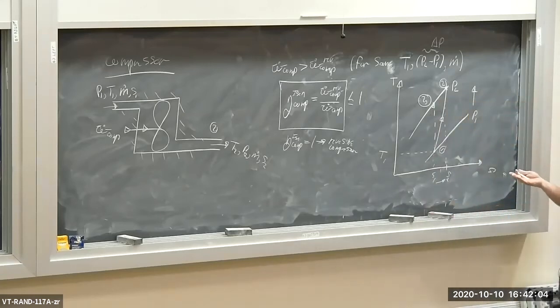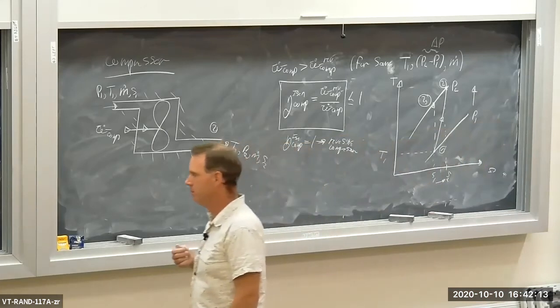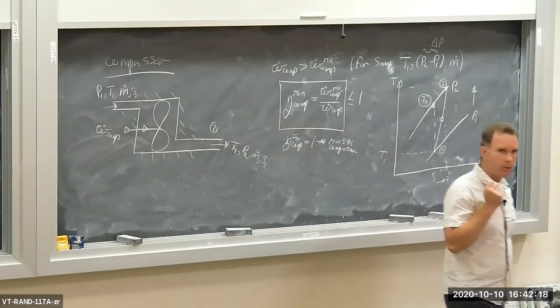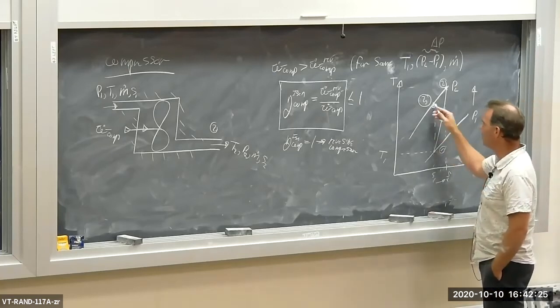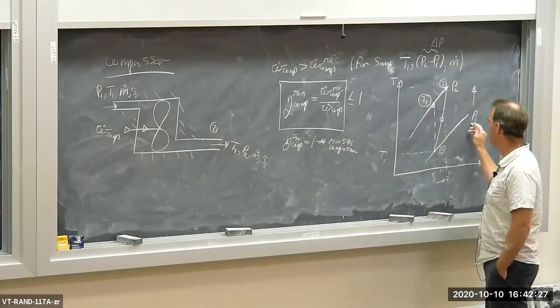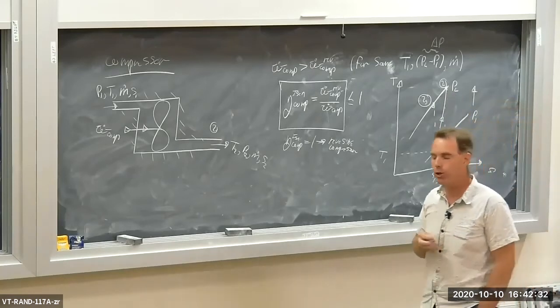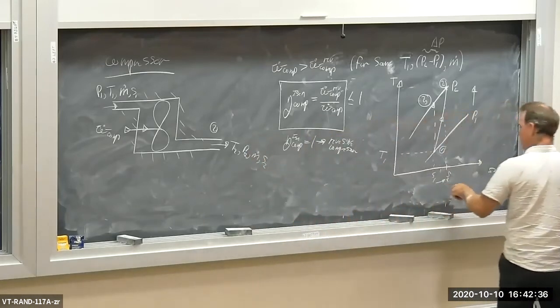So let's go over this again. We have two compressors. We have a real compressor, which is what we're interested in, and we have a theoretical isentropic compressor, which consumes the minimum work to pressurize what I'm trying to pressurize. The isentropic device moves vertically up on the TS diagram to get from P1 to P2. The real device has entropy generation occurring, and therefore S2 is greater than S1.